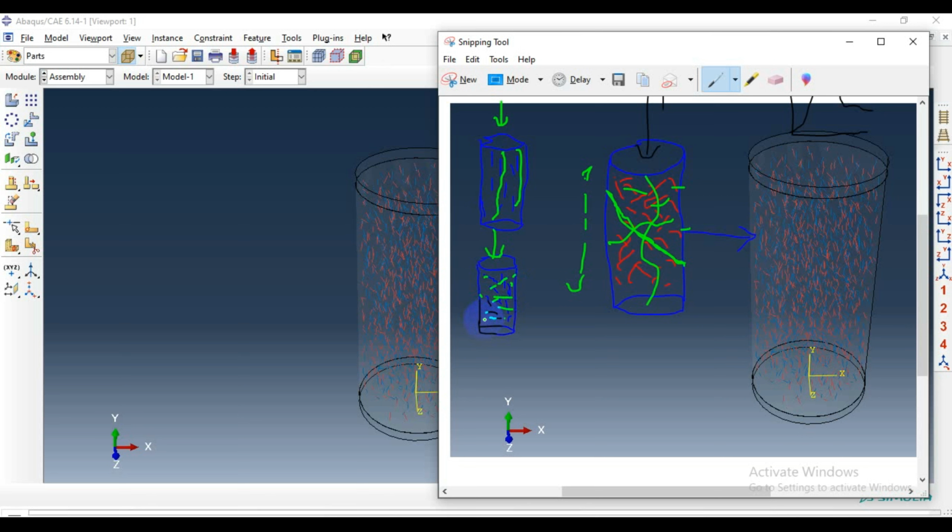But if flexural loading is applied, then this is not going to help you in the strength increase and enhancement. While for multidirectional alignment, in some applications, fibers are aligned in multiple directions to provide strength in more than one direction, which balances performance in multi-axial loading. So the process that we are going to enhance in terms of the properties, we are basically discussing this.